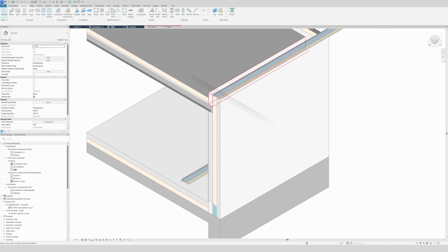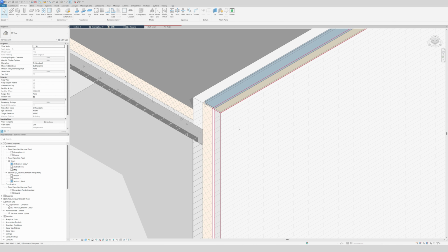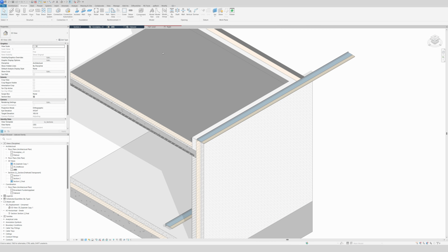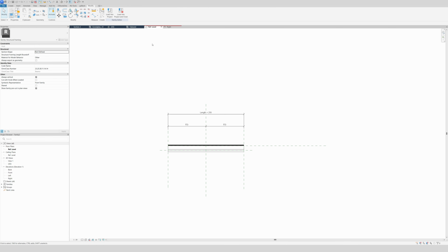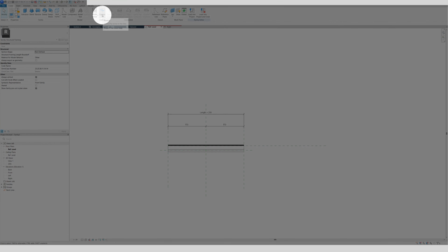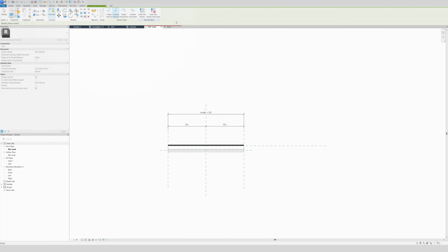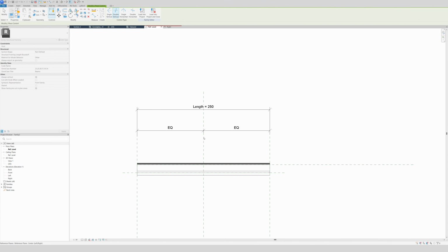Now 3D, well, that's not quite it. Well, no problem, I will fix the family for you, and you can just do the same. We go to reference level again, and to make it happen, you go to the create tab, and then you go to control, and then you go to double vertical, and you just click wherever you want, and voila. This means that you can flip it from front to back or back to front.